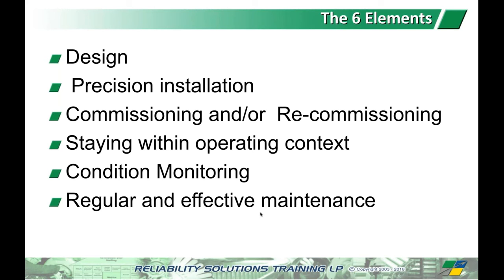The other thing is operating and staying within the original operating context. What happens a lot of times is we'll buy a system to do a certain job, and then after a year or so, we suddenly decide we want to increase the load, or instead of carrying 4 pallets, we want to carry 8 pallets, or something like that. And we never really go back and have a good, detailed look at the design of the system. And so we end up trying to operate the system outside its design parameters.